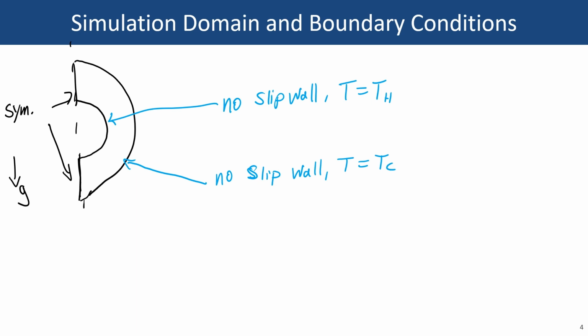We now have uniform fluid properties in that domain. We're going to need to list out a few material properties: the density of the fluid, mu, specific heat, thermal conductivity, and because we've treated this using the Boussinesq approximation, we also have beta, the volumetric thermal expansion coefficient.